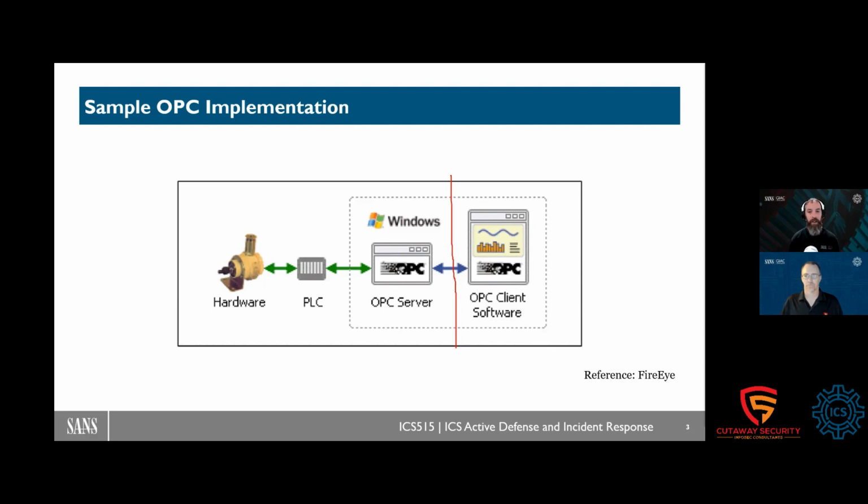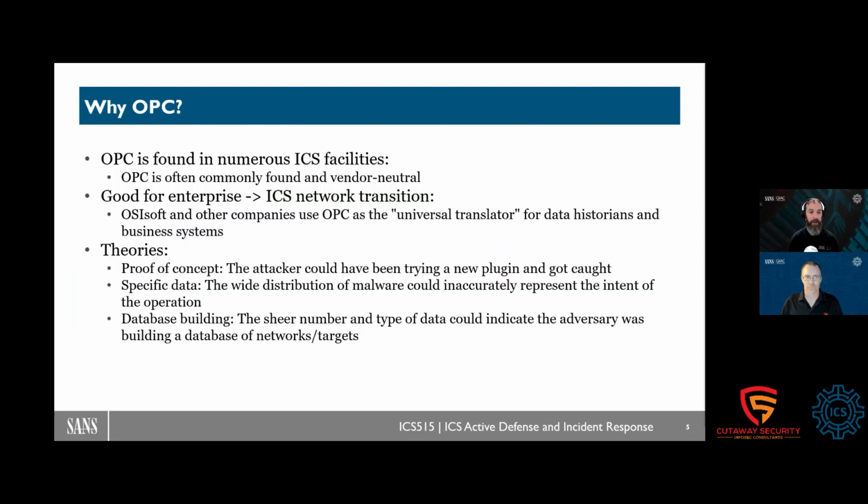And again, the reason that we talk about this a little bit more is around Havoc's. In the Havoc's case study, the adversary used and misused this insecure by design OPC Classic, against over 2,000 different victims that we know of. And it was OPC enum and establishing new OPC communications, learning the environment, again, that same capability of the data-rich protocol that is OPC, and especially OPC DA, where you're reaching in and saying, not only what is this parameter value, but now I've got a parameter value, a parameter tag name, a parameter description.